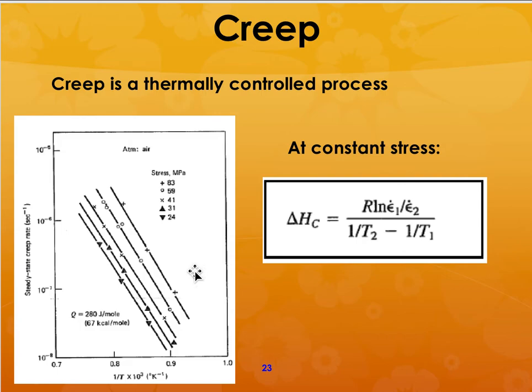So if you plot the steady state creep rate versus the temperature, here it is given in terms of inverse temperature in degrees Kelvin. R is a constant, and those numbers will be given to you.